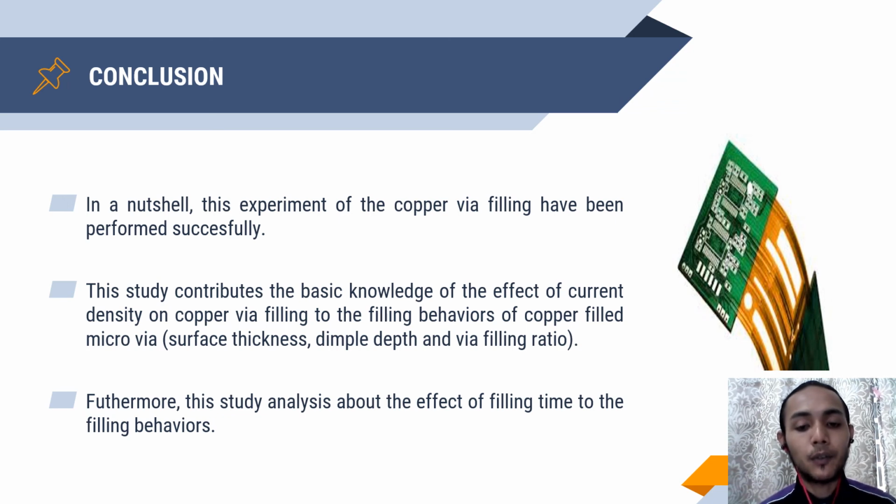And lastly, for the via filling ratio, as the filling time and current density increase, the via filling ratio also increases because more deposited copper ions enter the via.